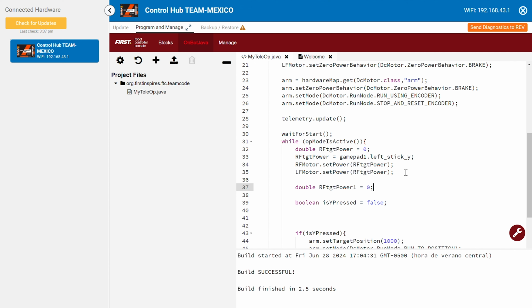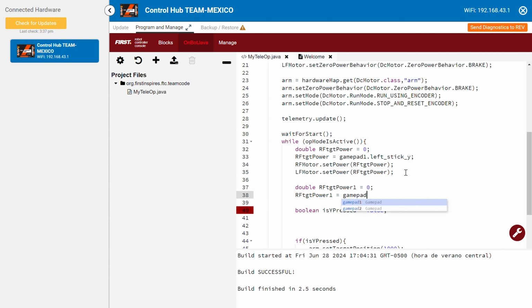Now your motor should move according to the joystick, and do the same with the second motor. Now to make it rotate, do the same process, but this time use the right X, and on the setPower put one of the two to a negative value. That way